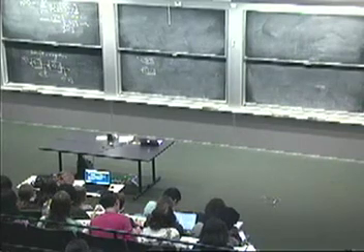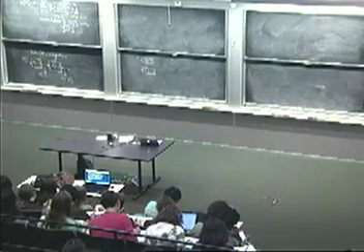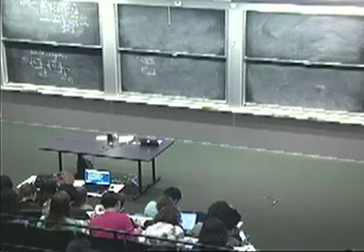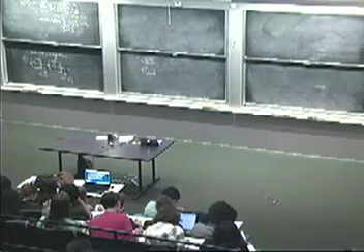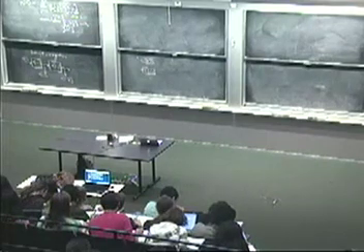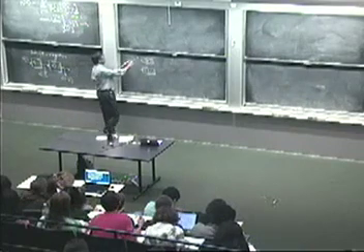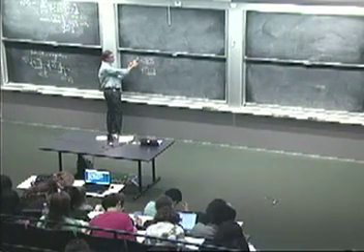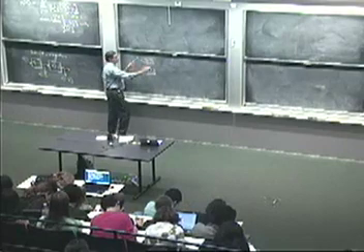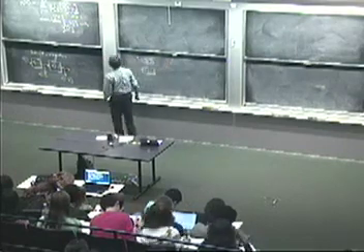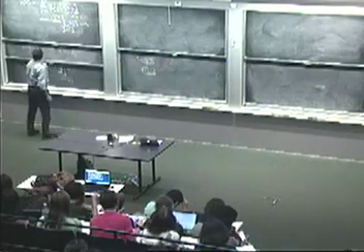We put the input that it takes to make that transition, and then after the slash, we put the parity bits that are emitted. So what we've got for the 1, 1 is the parity bits emitted when you've got input 1 sitting here, 0, 0 here, and you're using the parity computation that I had before.